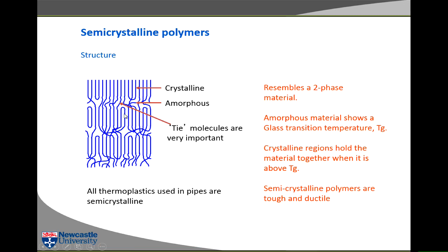The polymer physicists used to have long arguments about what the structure of these semi-crystalline thermoplastics looks like. You can use X-ray analysis. If you use wide-angle X-ray analysis, that will show you that the material is crystalline, and that the chains line up with each other, and it'll give you all the dimensions of the crystalline unit cell for the thermoplastic.